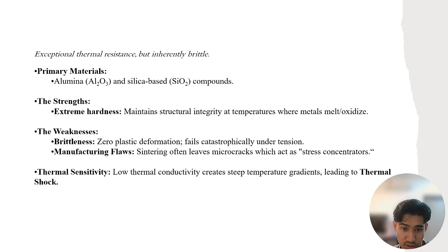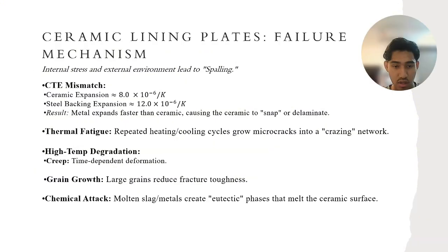The weakness: brittleness, zero plastic deformation, and it fails catastrophically under tension and manufacturing flaws. Sintering often leaves micro cracks, which act as stress concentrators. The thermal sensitivity: low thermal conductivity creates steep temperature gradients, leading to thermal shock.